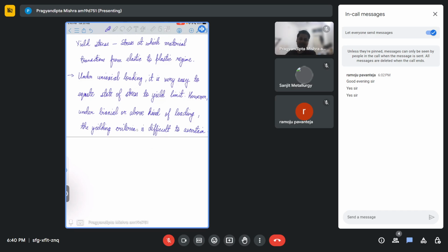There is something important that we have studied in the previous class known as Mohr circle, right? So if we draw a Mohr circle, let's say we are given a state of stress, let's take a 2D state of stress. Say we are given something like 220, we are given something like 50. Okay, MPa, let's say in MPa.